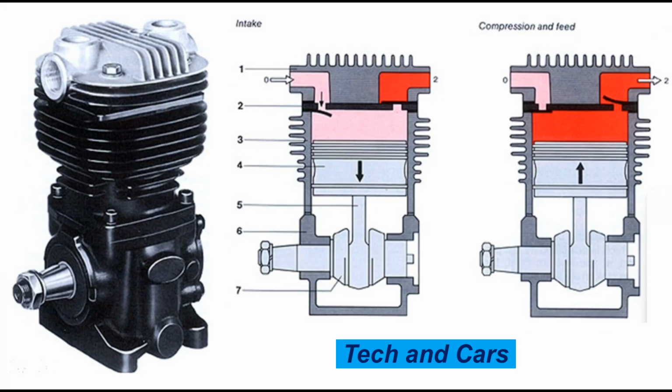In order to repeat the principle of operation of the air compressor, this is how it operates. As the piston retracts, the intake valve opens, allowing air to enter the cylinder. During this downward stroke, a vacuum is generated because the piston is withdrawing from the cylinder, increasing volume.